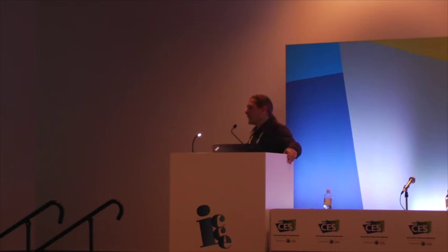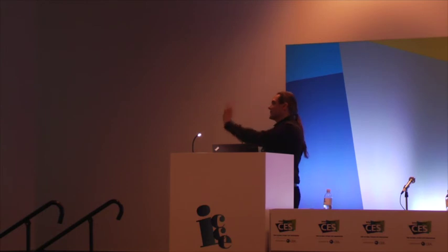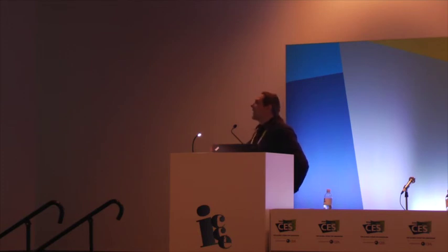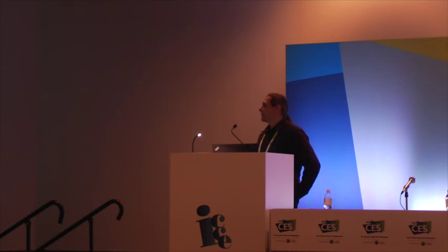Having now the components at one position, enables us, with the right ambisonics coefficients, to place virtual speakers anywhere we like. Therefore, if you remember the other slide where I showed you how a 5.1 could be realized using the MIMO system, now multiply it by the desired number of higher order ambisonics components, and then you have a version that could be realized nowadays and is also able to make acoustic rendering possible nowadays as well. I mean, it's a whole lot of computations that have to be done, but it is possible.